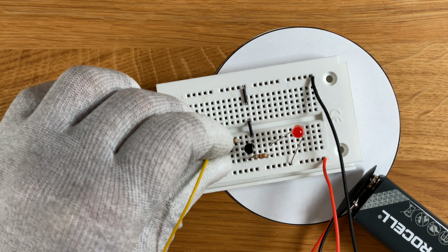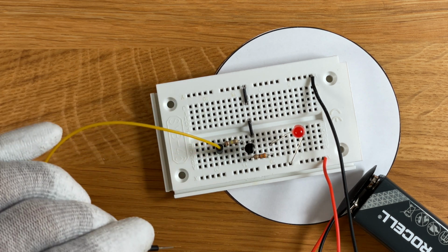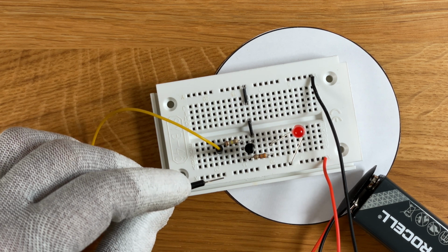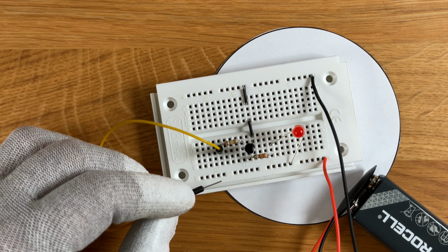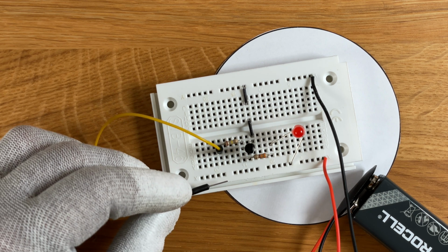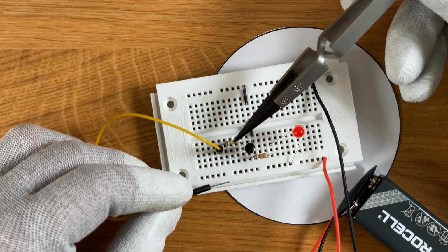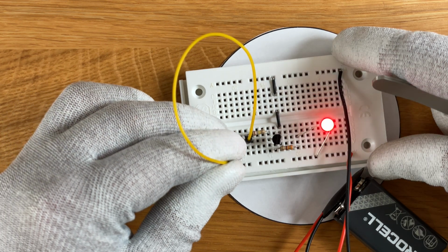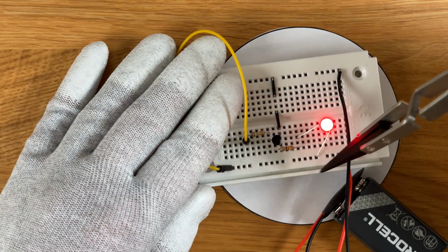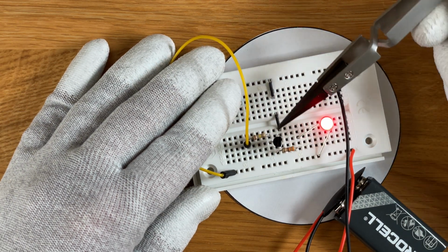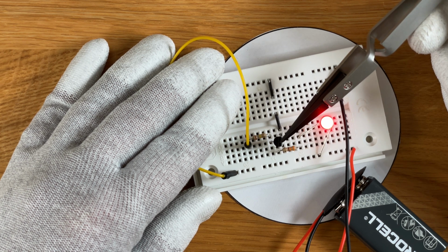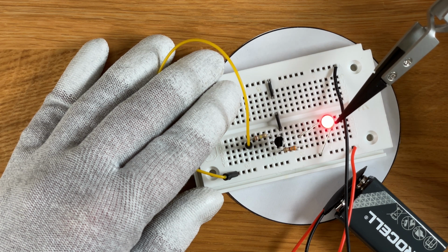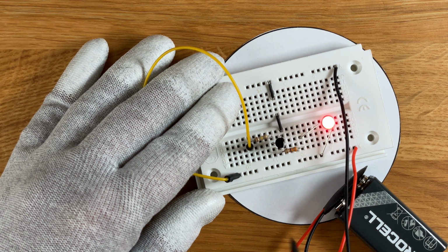And if we connect this yellow cable to one side of the resistor leading to the base and the other side to the battery voltage, then as we designed the circuit to be, the voltage is sufficiently high, generating a sufficiently high base current to make the transistor conductive, which you can see now as soon as we connect it to this power rail here, to the positive power rail. Now the transistor is fully conductive, and as expected, the LED is glowing in a bright light, indicating a sufficiently high current, just as we designed it to be.